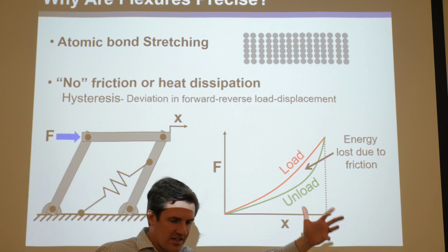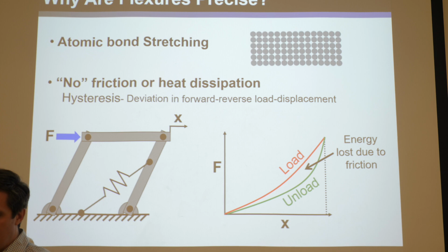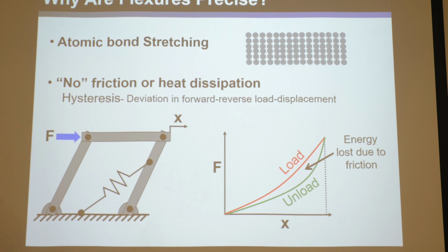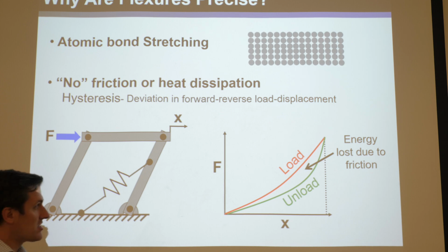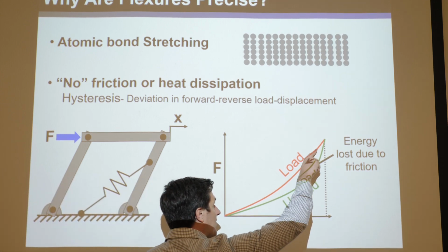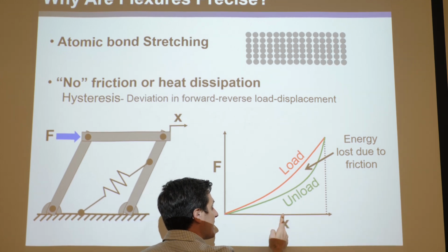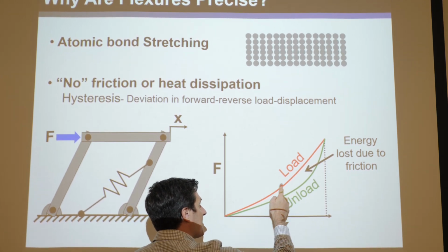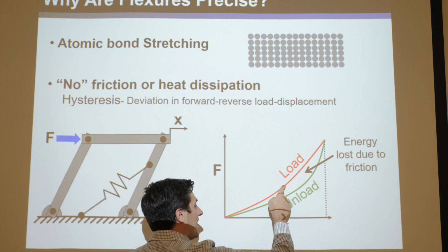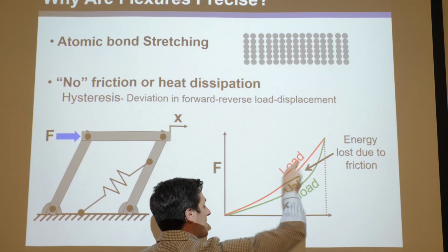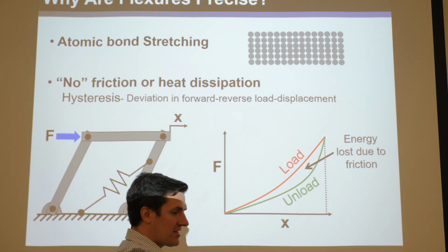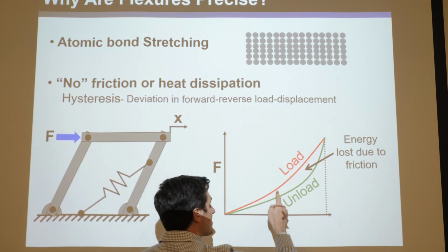Now, hysteresis occurs when, to know the state of the force and displacement, you have to know the history of its loading. So for instance, if this just loaded up and down along the same red path, then every time I said it was at this displacement, you would know it had this force. Okay? And you wouldn't need to know about how many times it was loaded and unloaded. You wouldn't need to know about its history. You could always map any displacement to any force.